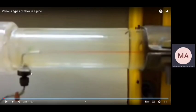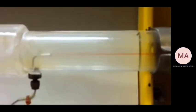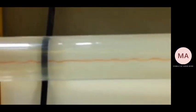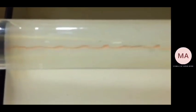This is a video of the dye visualization method. Firstly, it is a laminar flow. Then as time passes, it changes to a transition flow. This is transition flow, which is a wavy line of ink. Lastly, it changes to a turbulent flow, in which the ink is swirling in the pipe.